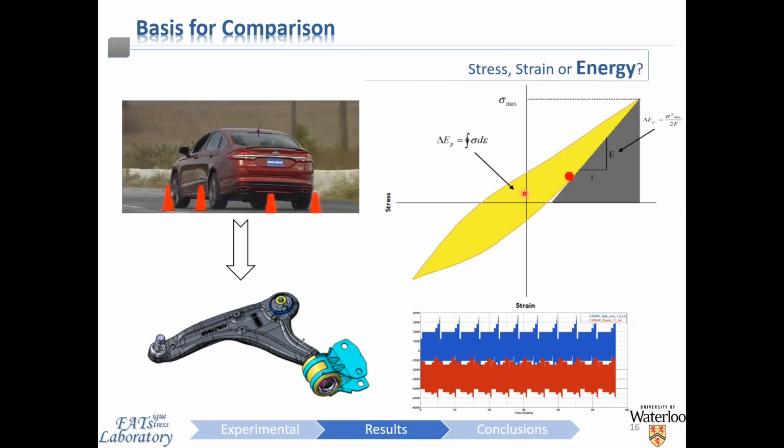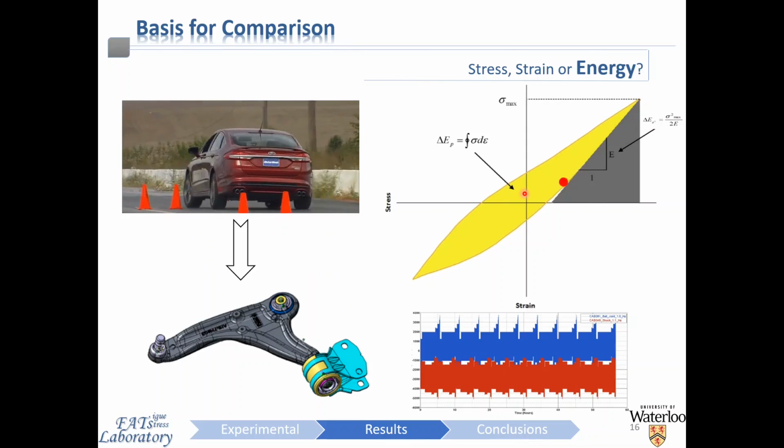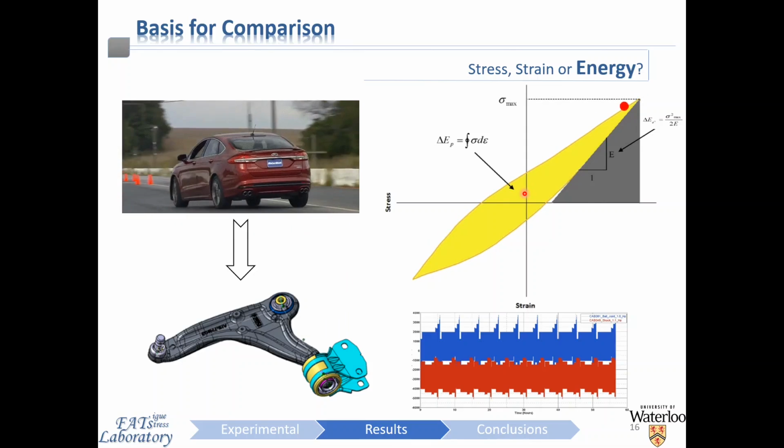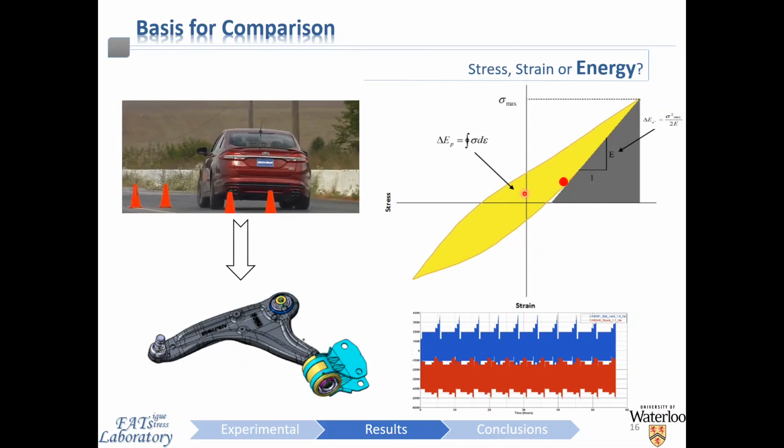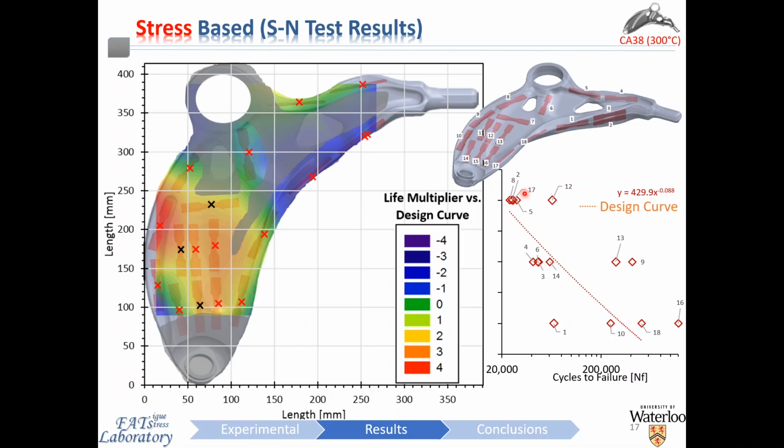And the answer is, well, it depends. I'll go through and discuss what these comparisons yield when looking at the full-scale control arm forging that we've discussed earlier, and the conclusions that we can draw from the spatial variation in the properties within each. What you're looking at here is the first case, a comparison technique by the method of stress control fatigue testing.